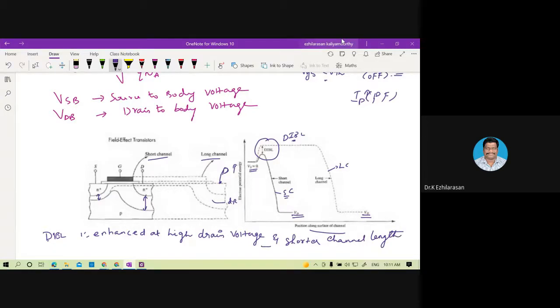Simply, when the source and drain depletion widths approach the channel length, that is, punch through occurs, then a large leakage will flow between the source and drain. The majority carriers from the source will be injected into the channel, swept by the field, and collected by the drain.